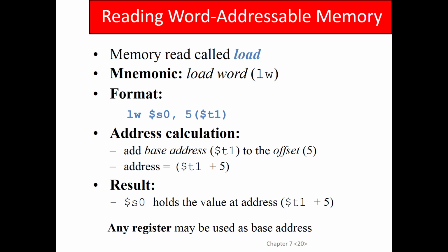So this is a good example because this shows you something that you would not want to do. Usually this number would be divisible by 4. But anyway, yeah, so the address calculation is you take whatever's in the base register and you add this number, right? Now, I used to always wonder, when I first started learning this, I looked at this and said, okay, yeah, that makes sense, but who sets the base register? And when?